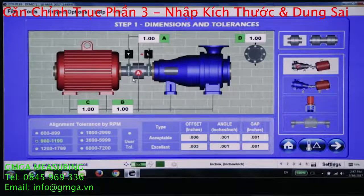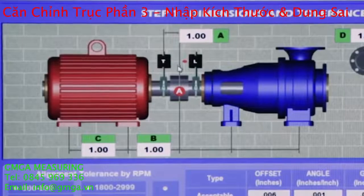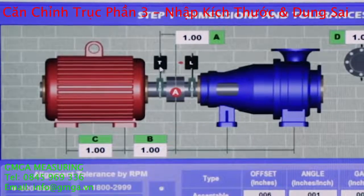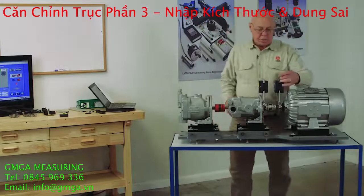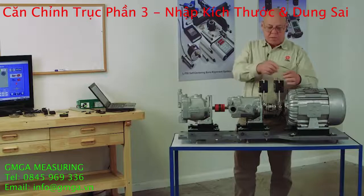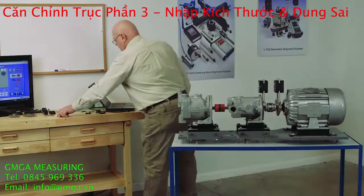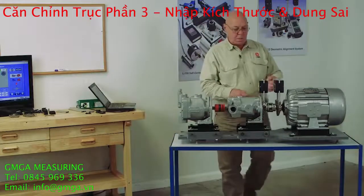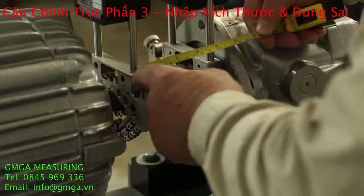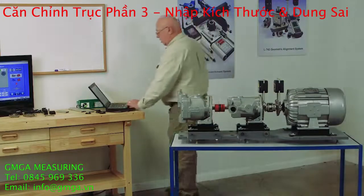Okay, so here, it's giving me these lines. It wants to know the dimension from the center of the coupling back here to the center of the target. And what I mean by the center of the target is these posts, in the center of the posts. That's where we're taking our measurements at. So that's where we want to measure to. So we take the tape measure and we measure from the center of the post to the center of the coupling. In this case, that's 2 inches.